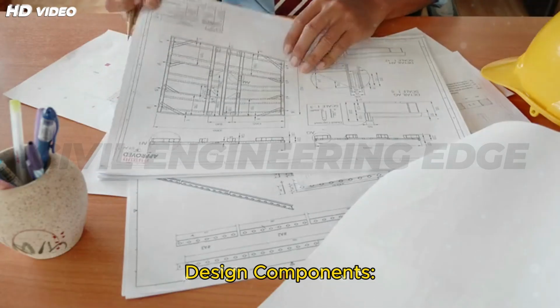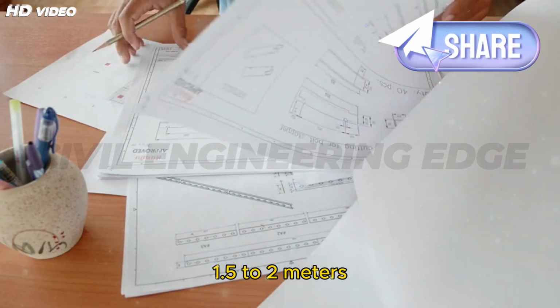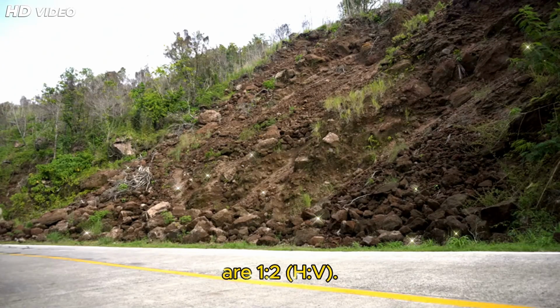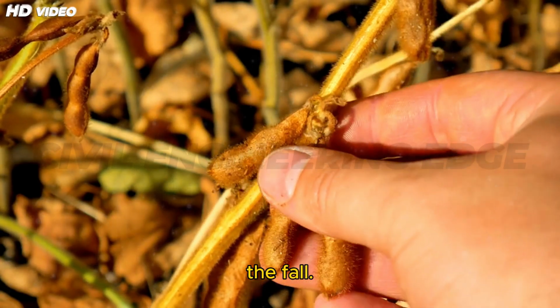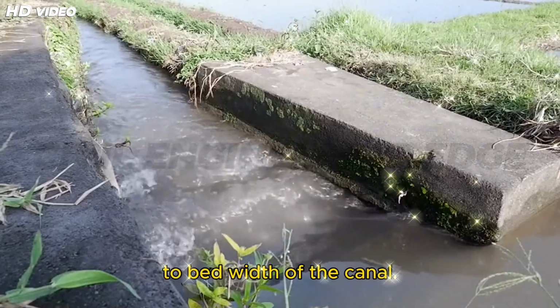Design components: notch details, generally 1.5 to 2 meters wide and 1 meter deep. Side slopes are 1:2 vertical. Multiple notches are spaced evenly across the fall. Crest length equal to bed width of the canal.